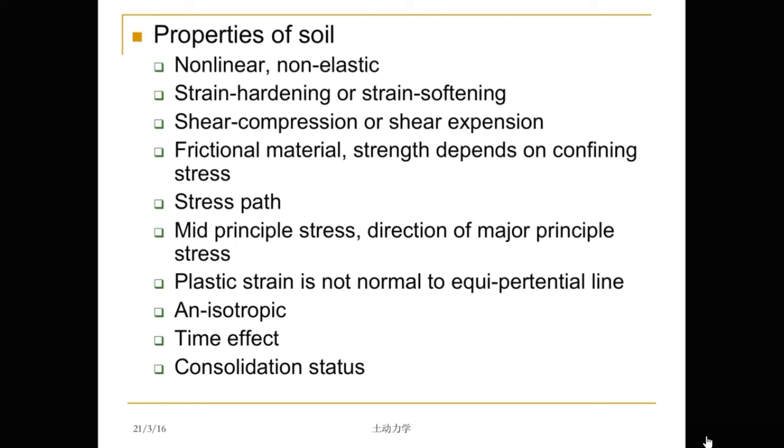Brought to a new location. Then, under gravity, there is excess pore water pressure in the soil. Then it is under consolidation. And after a long time, all the excess pore water pressure dissipates. The soil tends to become normally consolidated soil.